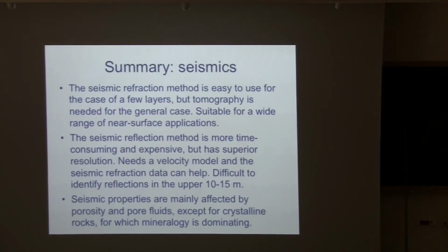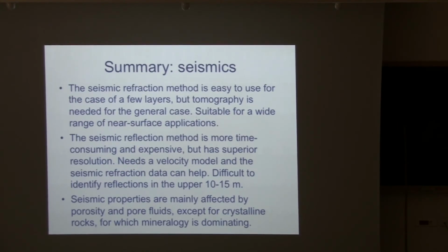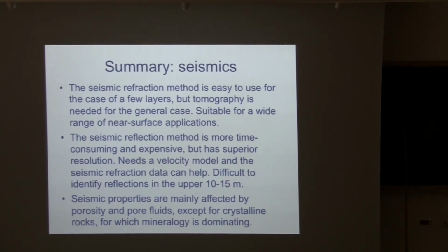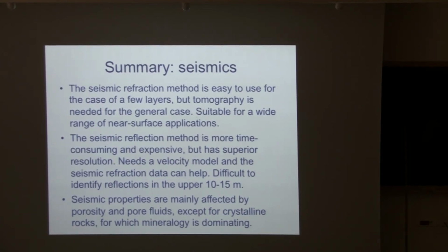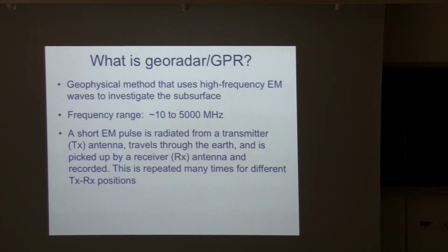So seismics, very useful in many ways, and I think I said this basically, but for unconsolidated rock, you're mainly sensitive to porosity and pore fluids, and then if you're in more crystalline systems, it's mainly the mineralogy that will dominate the response. So briefly here, I will talk about the GPR method, and then I will skip the gravity and the magnetics.